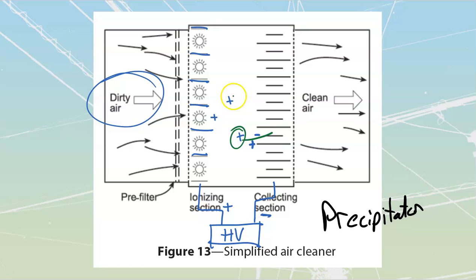All it is doing is ionizing the dust, and in doing so, it creates these particles that are charged, and they stick to it. You do have to take out your collecting section once in a while, and you usually just have to shake it off, tap it off over top of a dustbin or something like that. And then all of the dust itself is going to fall off. Some of them can be washed, depends upon how they're built, etc.